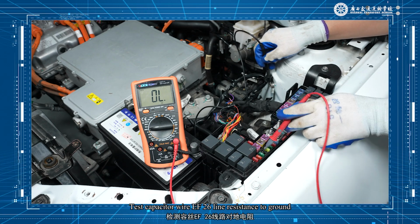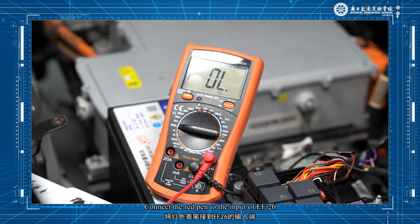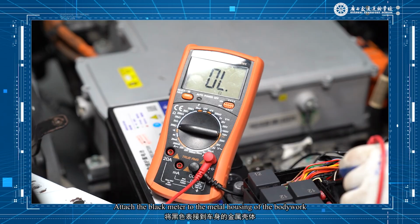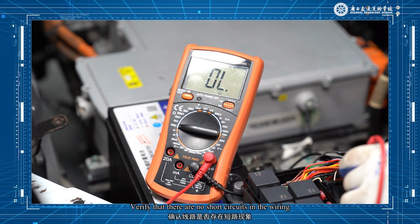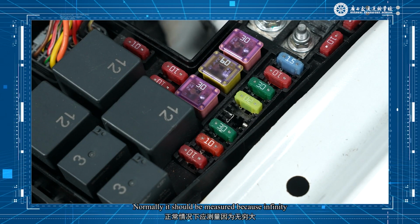Test the supply wire EF26 line resistance to ground. Connect the red pin to the input of EF26. Attach the black pin to the metal housing of the bodywork. Read the resistance value to verify that there are no short circuits in the wiring. Normally it should measure infinity.